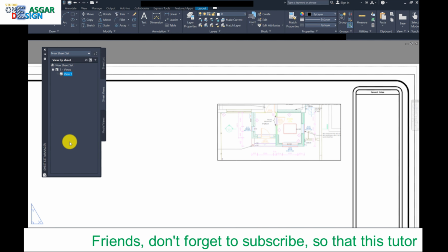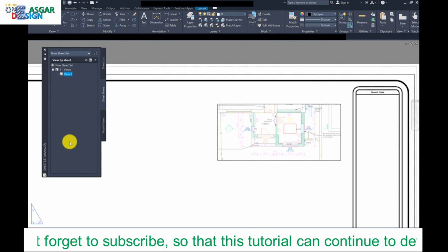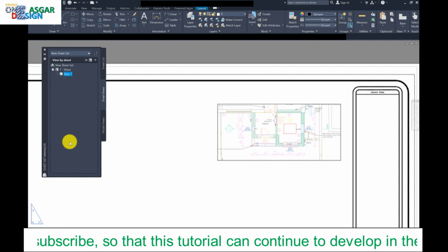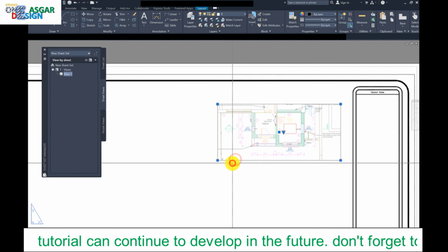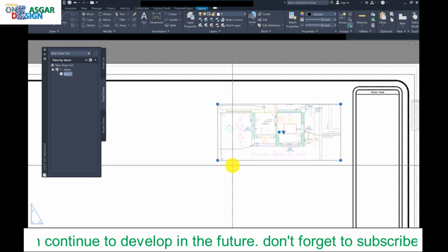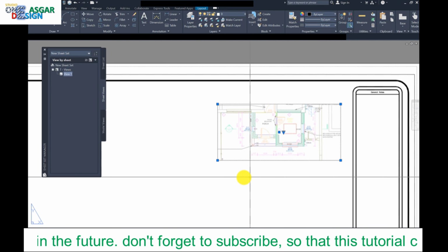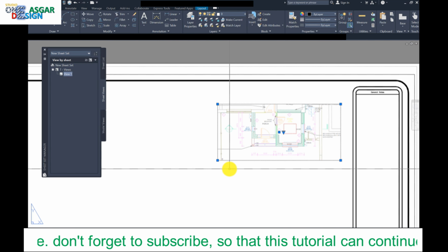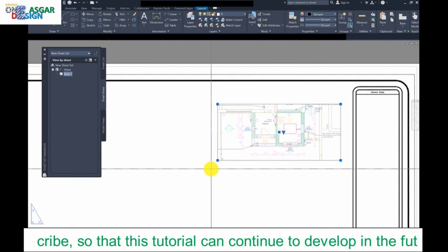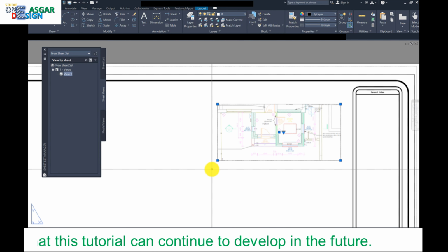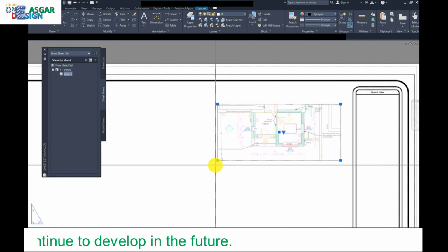So the sheet views tab will display an ordered list of views used in the current sheet set. You can organize these views under headings called categories that you create. When we created this sheet view and gave it a name, if you remember, the next title down was a category. That could be anything that you choose. If you're doing architectural, mechanical, or structural work, you can give it that type of category. Or you could use different categories like kitchens, bathrooms. It's totally up to you, depending on what type of sheet views you are creating.